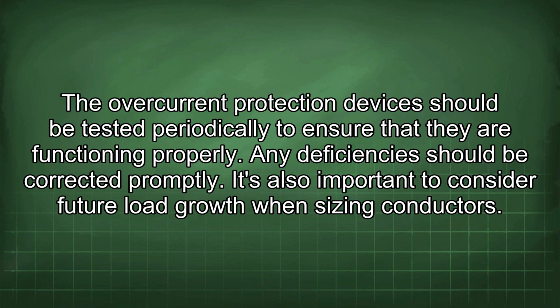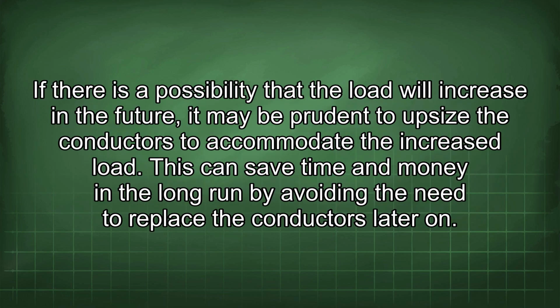It's also important to consider future load growth when sizing conductors. If there is a possibility that the load will increase in the future, it may be prudent to upsize the conductors to accommodate the increased load. This can save time and money in the long run by avoiding the need to replace the conductors later on.